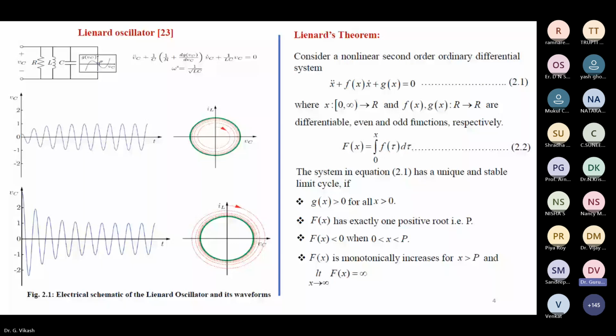That limit cycle will act like our modulating signal in the inverter control. Okay, so here the concept is the main thing. All this VOC concept is coming from a strong mathematical background. From that dynamics only, we are simply considering. Once we are satisfying our dynamics, satisfying the Liénard theorem, then our dynamics will give a proper stable limit cycle.